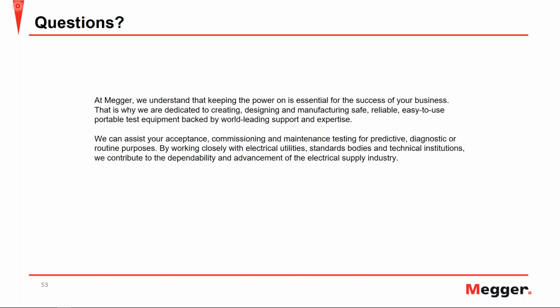The question was, are the Megger and other industry available PF temperature correction factors the same? Yes, so initially there were, and there are still, some tables available that were developed from databases of transformer results from years and years of data collection.